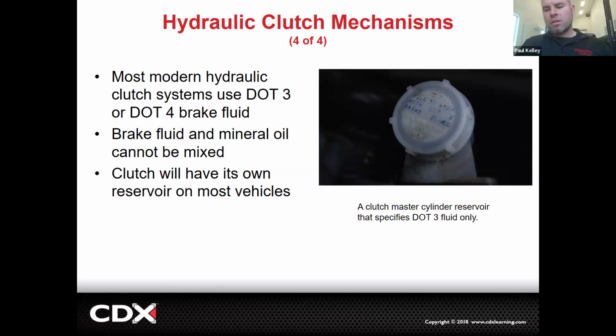Once in a great while, they'll have some abnormal clutch fluid. If it's mineral, it's a no. Don't mix them. DOT 3 and DOT 4 can be mixed, but it lowers it to the standard of DOT 3. Makes sense? But once in a while you have a clutch that'll use a different type of oil and it would specify it. So this one is saying DOT 3, so we're good there.